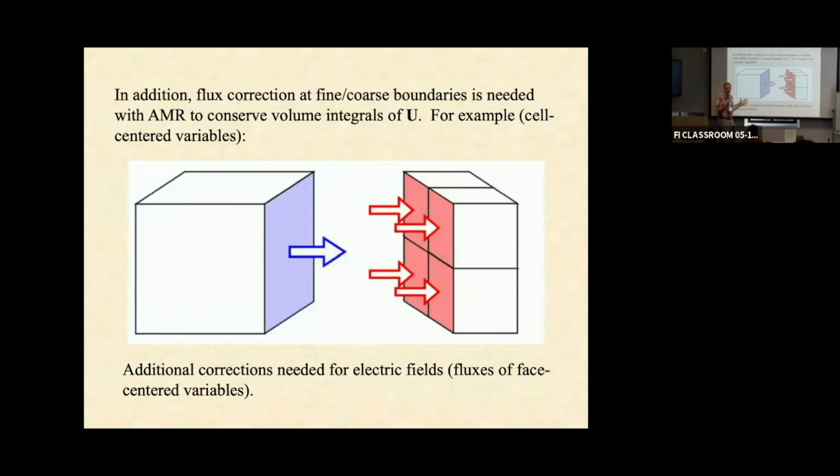So at the boundaries between fine and coarse meshes, that's the one location where you do enforce the boundary conditions via the fluxes and by your neighbors. And that's crucial to make sure you have conservation and prevent spurious reflections at fine-coarse boundaries. Yet another communication step is required in AMR, because generally these blocks are on different processors and you've got to move the fluxes back and forth.